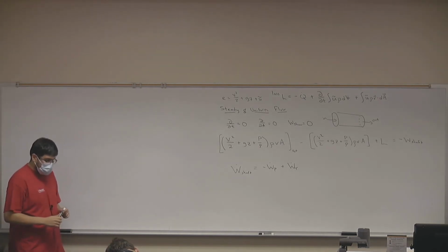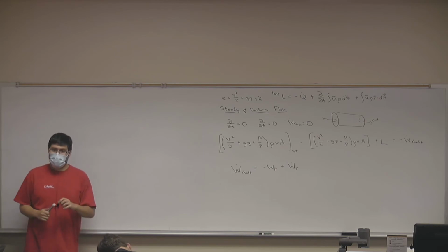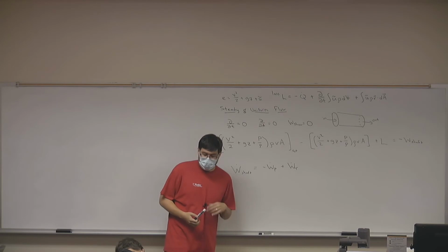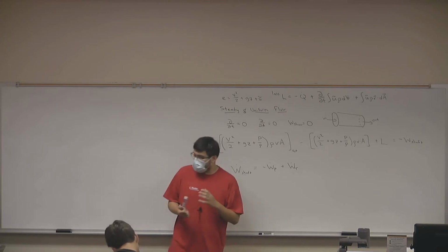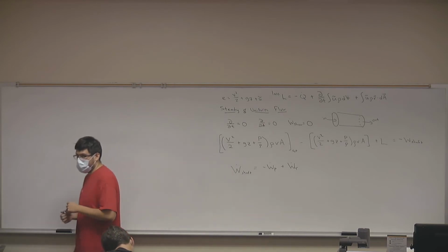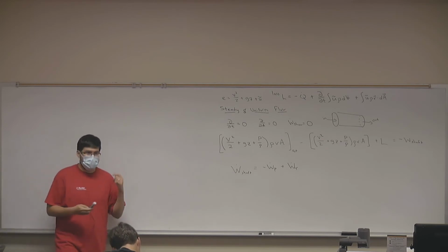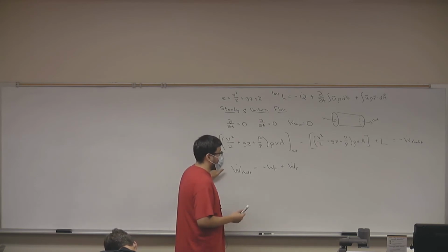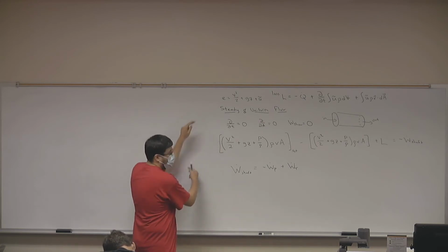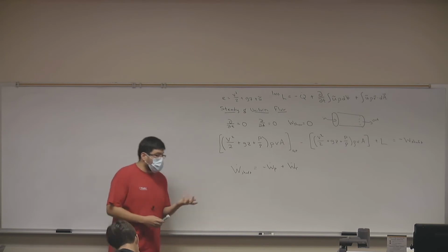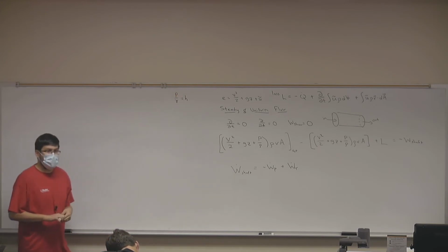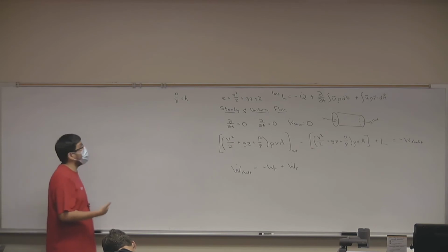But let's think of, for example, flow in a pipe system. Earlier this class, as in several weeks ago, we learned of an instrument that we can use to measure pressures in the pipe. Do you remember what that instrument was? Manometer, right? And manometers allowed us to figure out the pressure in a system based on a depth of liquid. So essentially, when we look at a manometer, we're expressing our pressure in dimensions of length, right? Simply a length of water or a length of a fluid.